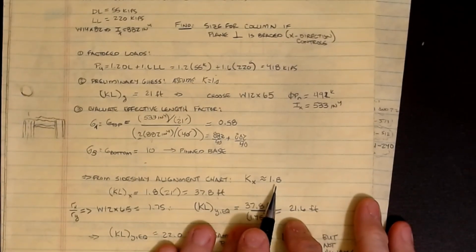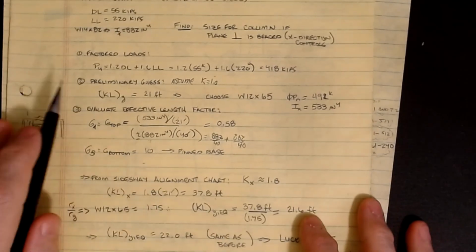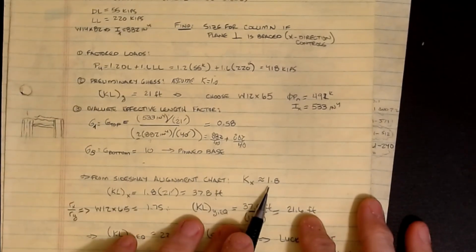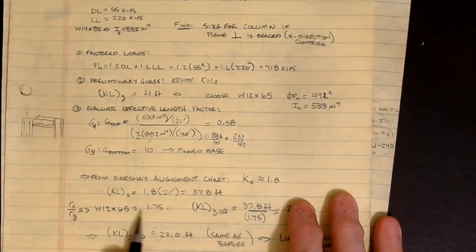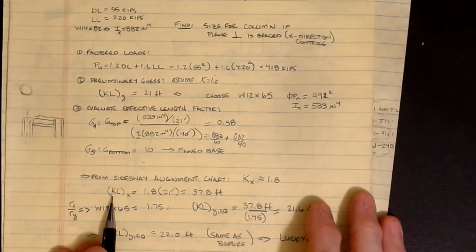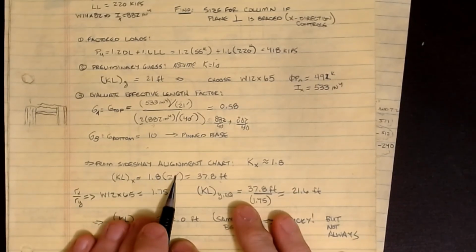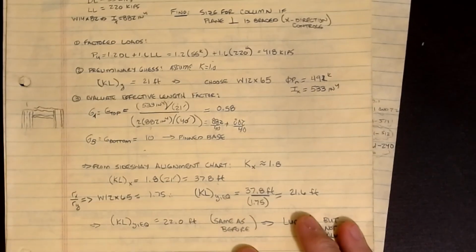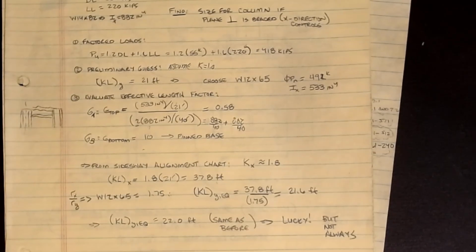So now we can go in and take a look at, because we've assumed that the plane is fully braced out of plane, we sized it for a weakness in the Y direction, okay? But remember, those tables only work for the Y direction. So what I really have to do is I now have to turn around and calculate the KLY equivalent that we talked about a couple of videos back. So the KL for the X direction is now 1.8 times its length, 21 feet, is 37.8 feet. Okay, and then for my W12 by 65, and I lost my page again. Let me flip back to that. We're back up in table 4.1 on the 12s.